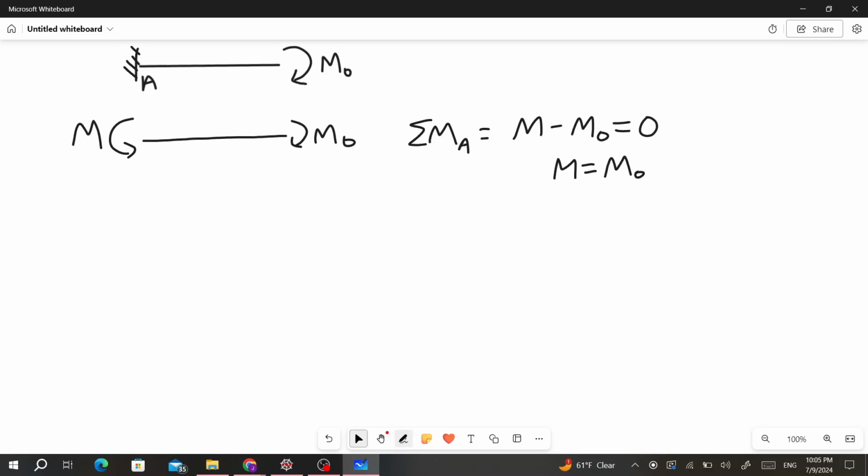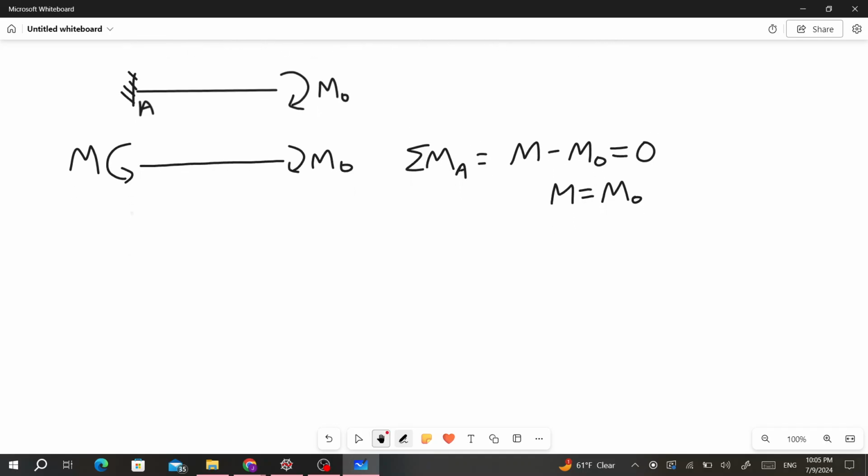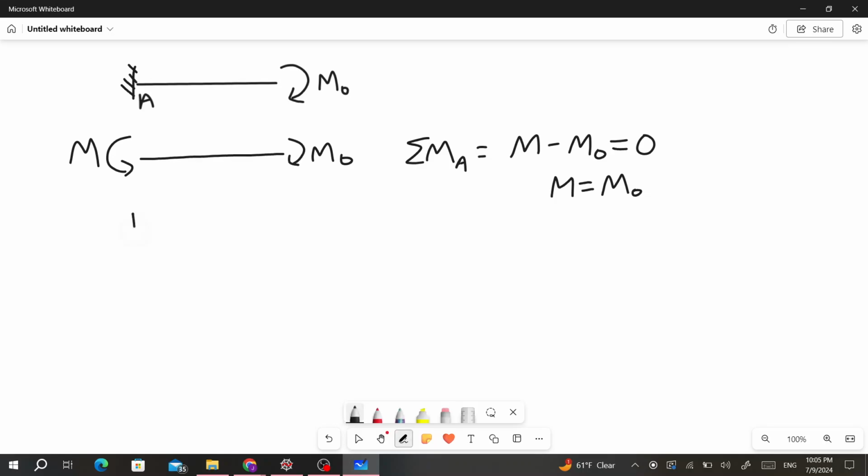So our shear diagram, there's actually nothing there this time because we don't have any shear. When we just have an applied moment, there's no reaction load. So when we draw our shear diagram, there's actually nothing happening. We just have 0 all the way across the beam. Because there's no applied shear forces, there's no reaction in that direction, so there's nothing on our diagram for V.